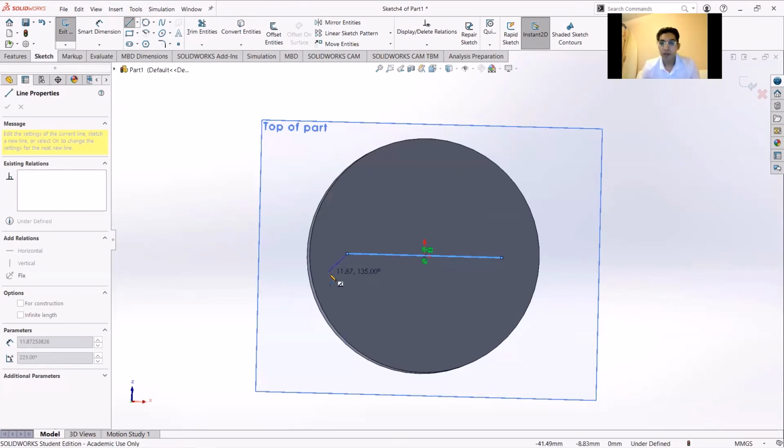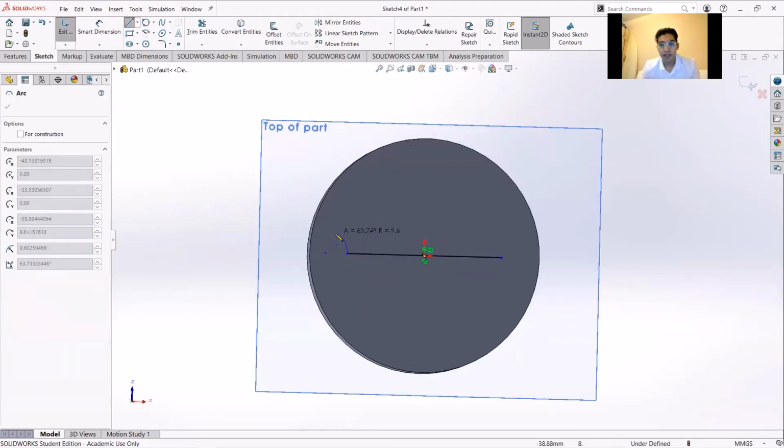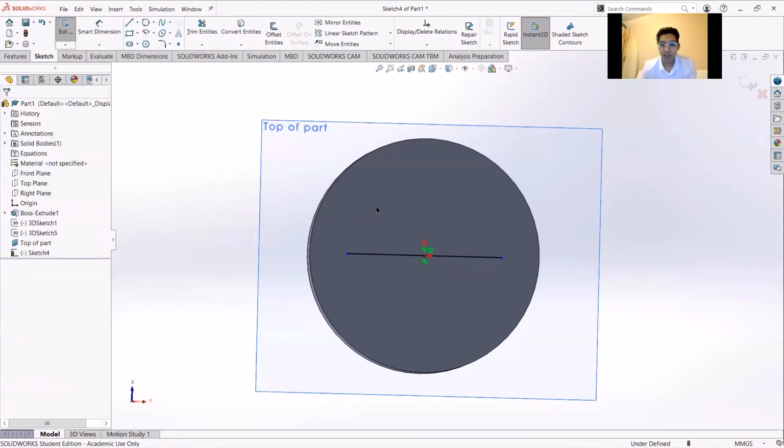So if you notice, right after you made your midpoint line, it's not gonna let go. It's gonna assume you're gonna keep going. So you pretty much have to have your finger near the escape button to not continue making lines. So if you hit escape, it'll let you move your mouse without clicking on anything and making extra lines.